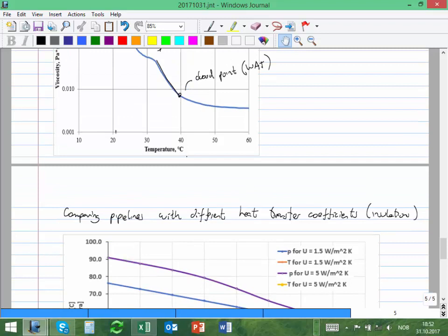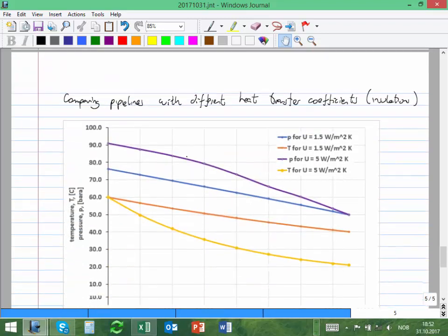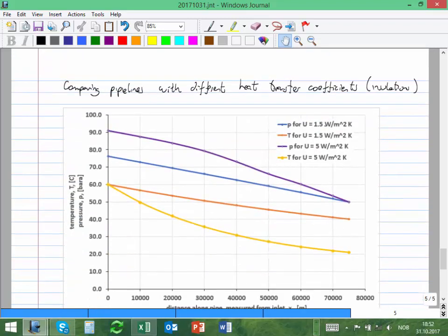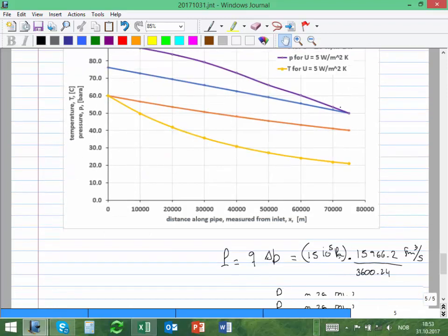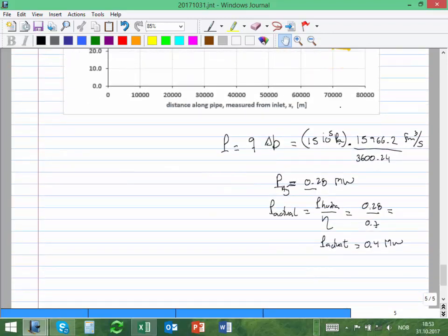Okay, see that? So in that case, I will try to squeeze my boss to go for this very expensive insulation. There are some insulations that make pipe in pipe. So one pipe is outside, you have vacuum, and then you have the pipe inside. All kinds of tricks, but this analysis can help you to decide on that. And this power is so high not because of the delta P, that's relatively low, but because the rate is huge. Okay, this rate is huge.